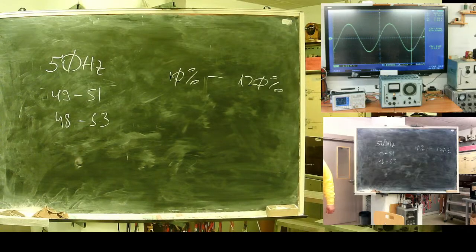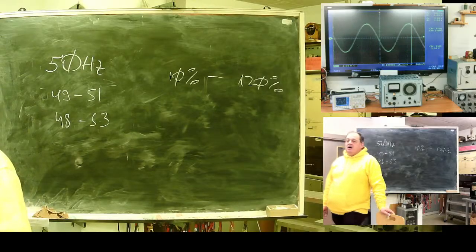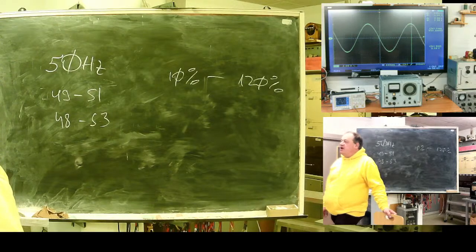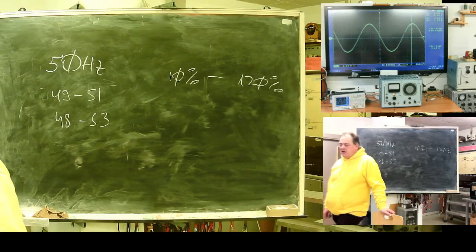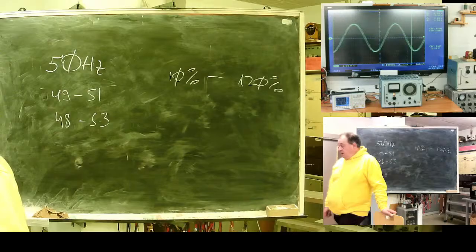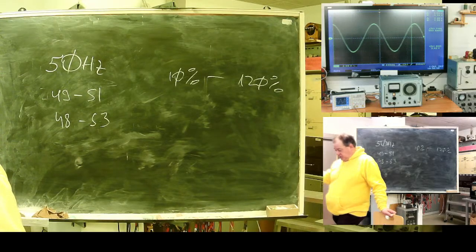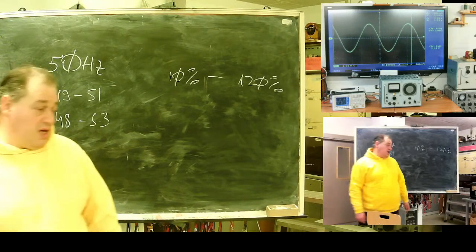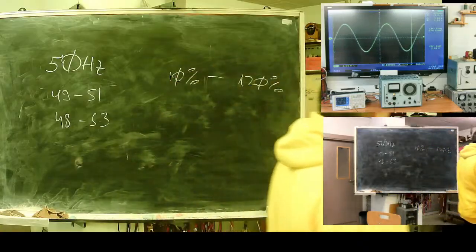It depends on design. Some large turbines with direct drive, synchronous or asynchronous machines, are not so tolerant to high rotation frequencies. Some allow up to 200% if there is an inverter in the middle of the power supply.